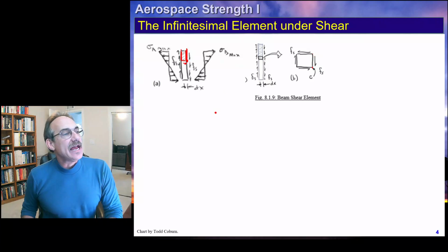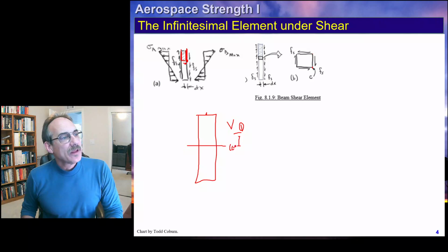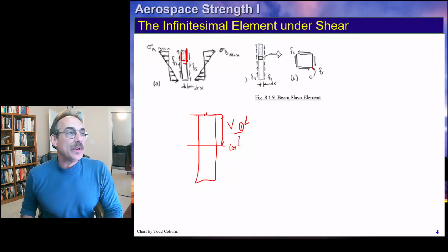If we take a look at this slice, we're actually going to evaluate, looking at the end of this thing, we know the shear stress here is 0. Remember, our shear stress is VQ over I, or our shear flow. At this point, if here is the centroid, the CG, and if we cut that off parallel to the CG, there's no area above this. So this Q has a 0 area. It has a large Y minus Y bar because the Y value is this dimension here. That's large, but the area past this point is 0, so the shear flow here is 0.